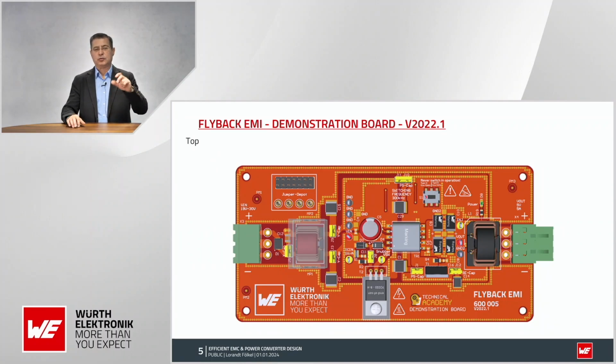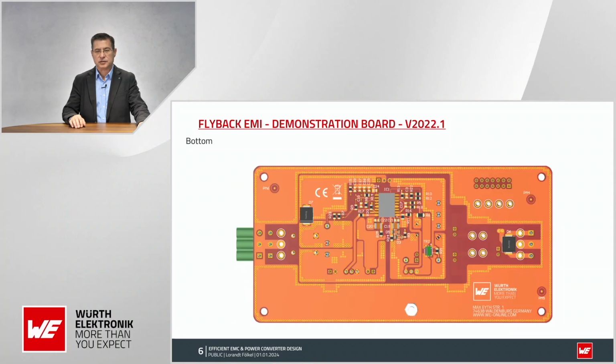Also the common mode choke can be taken out and replaced by two jumpers to use it without any filter effect. So this is on the bottom side again. You can see we made a PE around the board, a nice good grounding, a lot of wires, using polygons of primary and secondary, and the idea was to achieve good EMI and to be inside the norm, to not make too much noise in conducted emission or radiated emission.